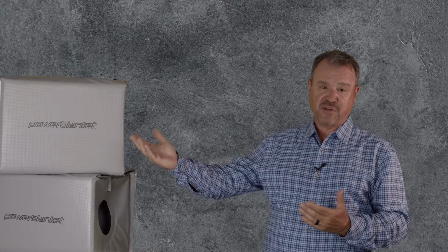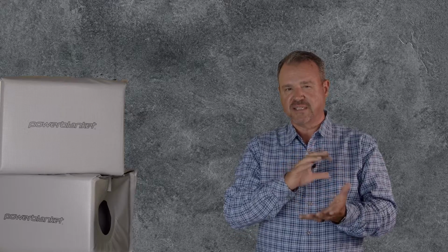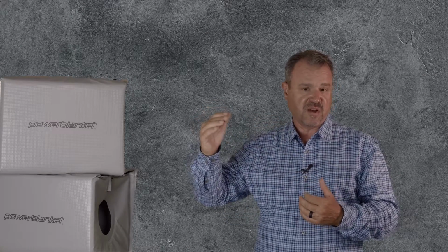Circulation heaters as a process heater are really pretty sophisticated, like I mentioned before. They take a high level of control. When product is flowing through our heater, it's usually going to some critical process that has to receive its product at a very precise temperature. So the control system on a circulation heater really needs to modulate that heater at a high rate and make corrections if the flow varies a little bit or if the temperature needs to change at the process.